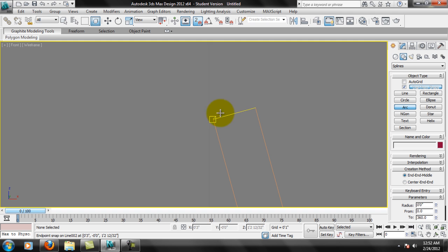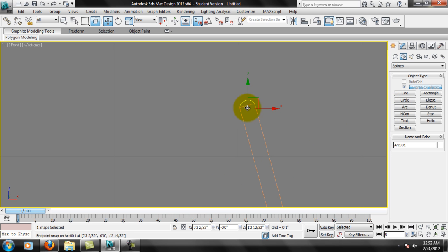So I'm going to click and hold and go to this point, and then come up with this edge here to give this somewhat of a rounded top. Okay. And then turn off the arc by just hitting escape, and I'll hit S to turn off snaps, so that snap goes away. Okay, we've drawn this line. It's not actually connected. You notice we have 2 separate objects here. So you need to select either one of these.